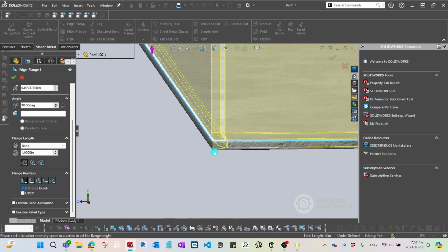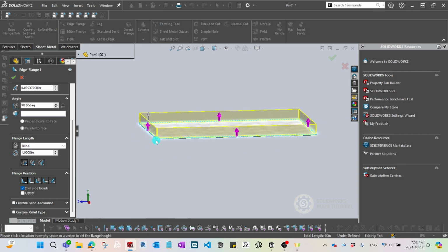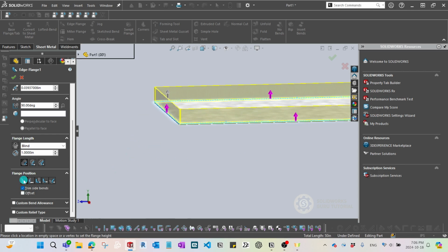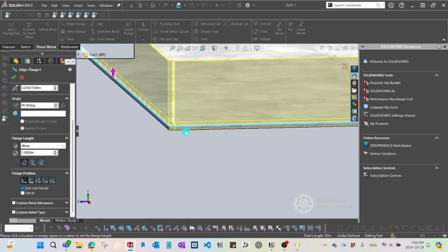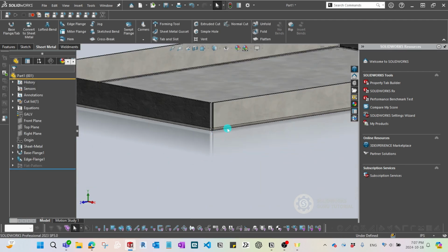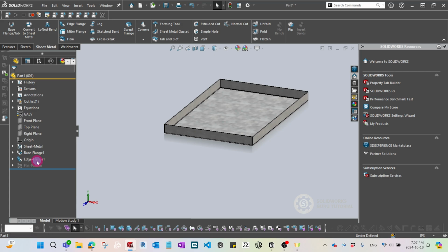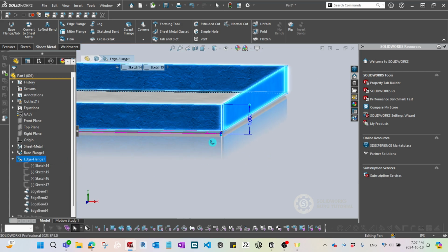But for us, we want to make the outside to outside face dimension accurately the nominal value, which is 10-inch. So we're going to use the first option. And then we also want to check for trim side bands, so that it could show some kind of clean bands, corner point, like this. Okay. However, there are some values that I want to make some adjustment to.